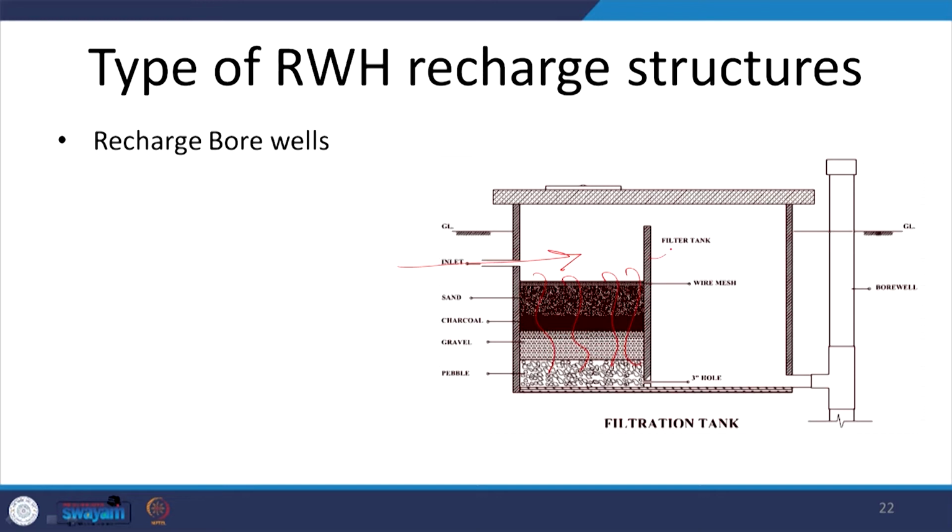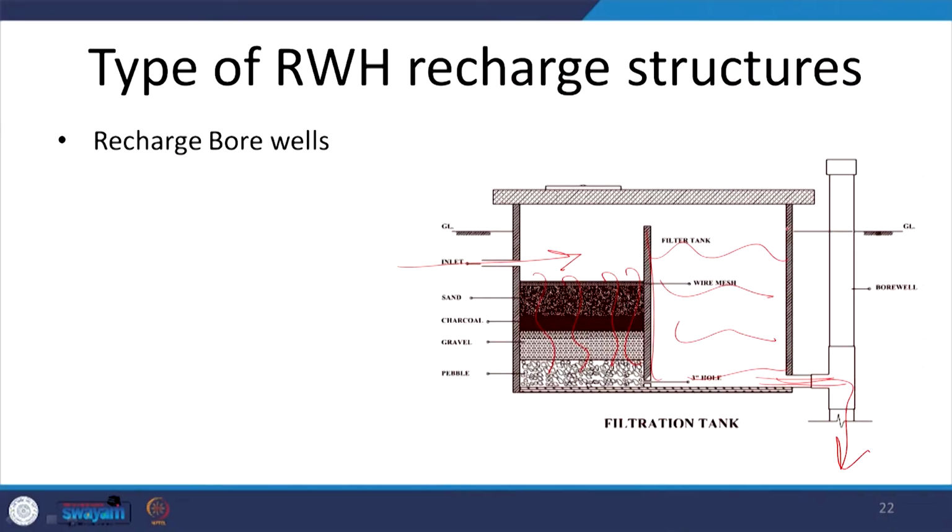So, we can actually store the water and this water goes through this bore well which is connected to this tank. Generally what happens is that during monsoons even the earth is saturated. So, we are not able to pump in or recharge a sufficient amount of water to the underground aquifer. Here in this case, if we store this water, it may actually be recharged through this bore even later.